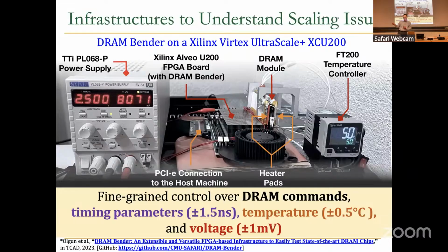So we actually built a lot of infrastructure in my group to understand these scaling issues. This is one example. There are FPGA-based infrastructures where we can attach memory to programmable memory controllers. And with these programmable memory controllers, we can program and test different timings to memory, test different temperatures, test different voltages, and access memory using different patterns so that we can understand what's happening in real memory devices.